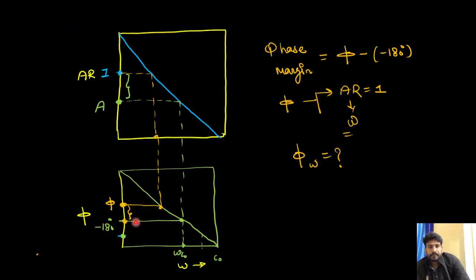This is the last topic. Now, what about the gain margin? Put phi equal to minus 180. Whatever frequency I get when I put phi equal to minus 180 is my crossover frequency. At this frequency I will calculate the amplitude ratio AR, and the reciprocal of this, one divided by AR, is the gain margin. This is the formula.